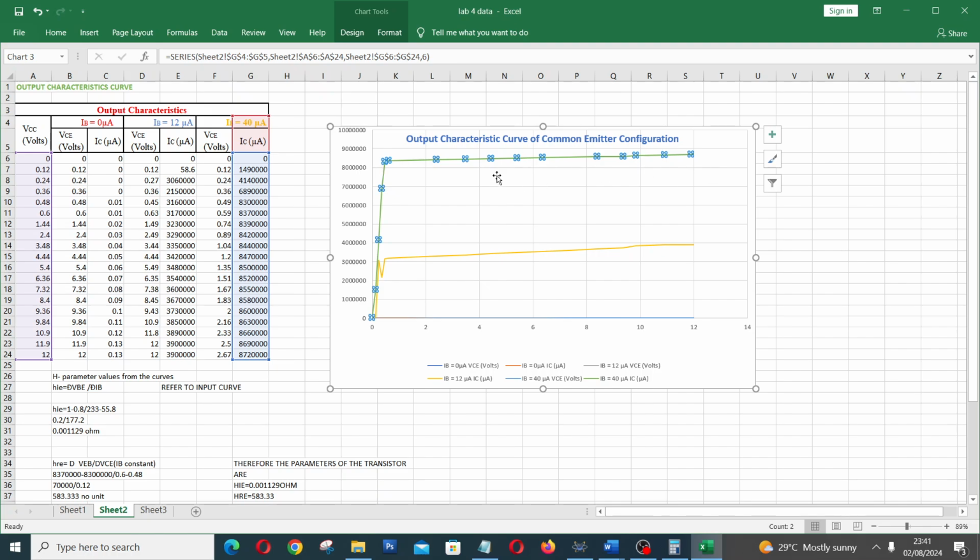This one now, the slope of this part is 0 because there is no change in the y axis. But where you have a linear part is where you can find the slope. That's why I'm putting this point and this point. Whatever value I pick here, that's 83,000. If I pick the second point here, 41,400. So that will be y2 minus y1. Then what's the value is 0.24. What's the x-axis value is 0.6. So when you calculate it like that, you get this particular value.